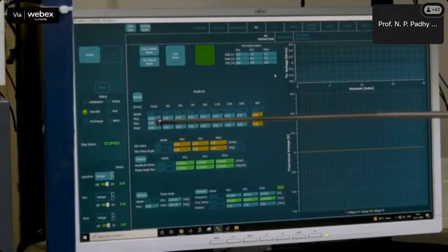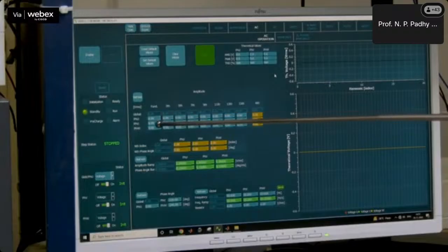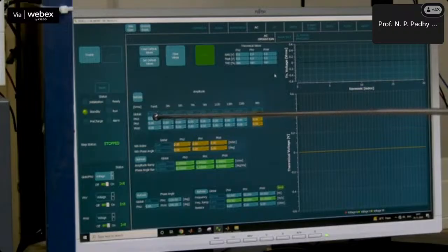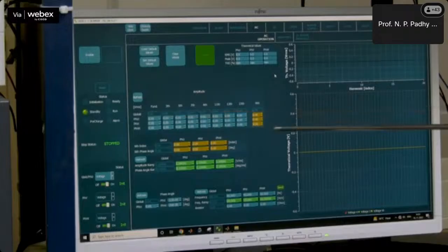Desired voltage values need to be entered for the 3 phases in the AC operation section of the software. Apart from just entering desired voltage values, it is also possible to monitor grid voltages during experimentation. After entering desired voltages in AC operation, the voltage and current limits need to be specified in the limit section to ensure the safe operation of the system, or in other words, so that it does not exceed the operating voltage that you desire during the experimentation.